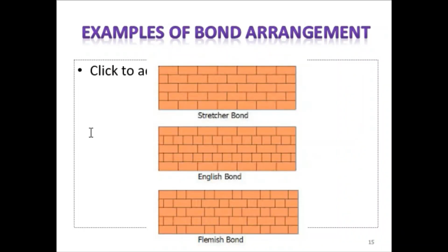Another important thing is what type of bond arrangement. Is it stretcher bond, English bond? If you notice, the stretcher face with the header after that, and then stretcher face again, then header face. Or Flemish bond, where you blend both stretcher face with the header, stretcher, and header again. So we need to specify so the contractor knows which prices fit the type of arrangement.